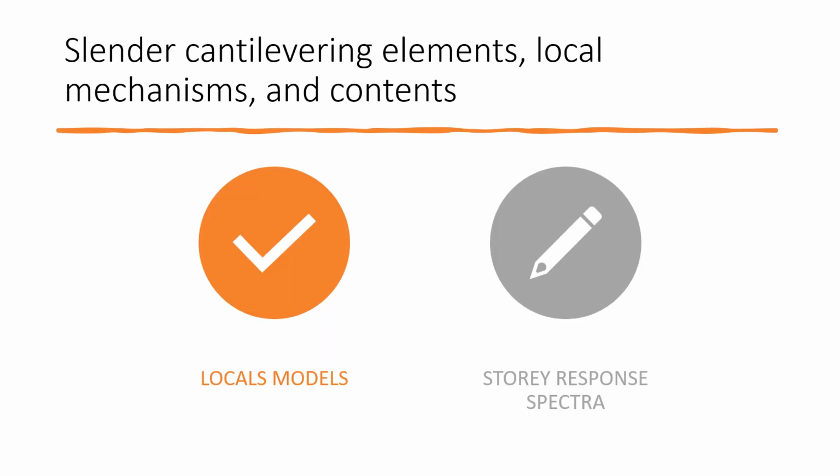Another aspect that needs to be treated outside the classical pushover approach is the assessment of slender cantilevering elements or local mechanisms, effects of contents, that require the use of local models.